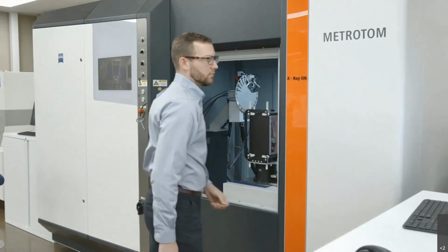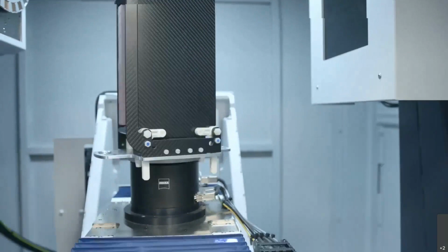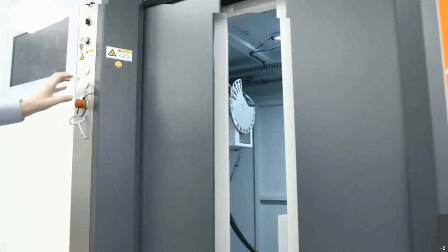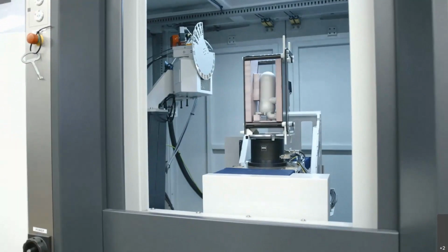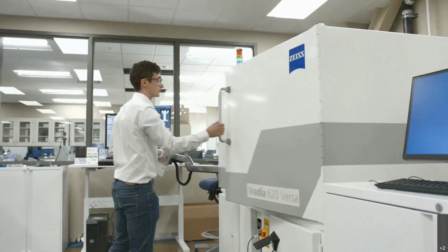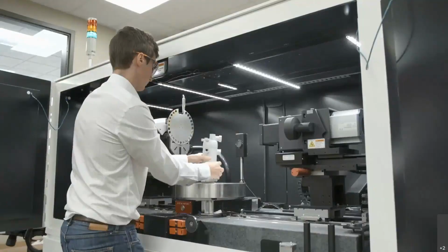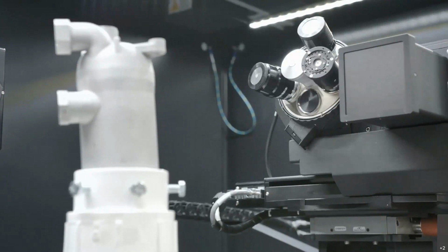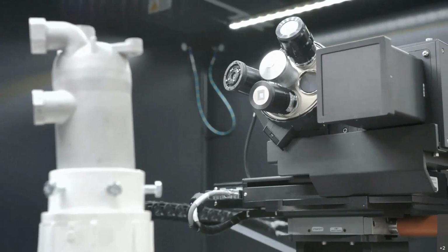In order to get the internal defects, we scanned the same part with the CT system, where we can look not only at the surface but also at internal defects, and we can also do metrology using CT data, because this system is called Metrotome. It's designed for metrology and tomography together. Then, having identified large defects, if you want to understand features at lower resolution not being captured by CT, we use micro CT to show that image of the same part without cutting it open.